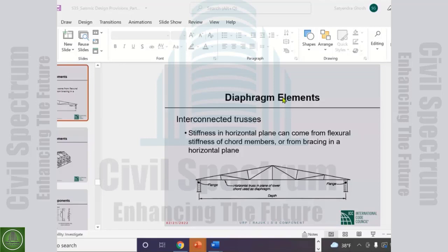I have no reason to believe it is incorrect. I mentioned many times, even when you have shear walls and frames in the same building, near the very bottom of the building, almost the entire story shear goes to the shear walls and very little to the frames. This is why in a dual system we do the second analysis with the frames carrying 25% of the lateral forces.